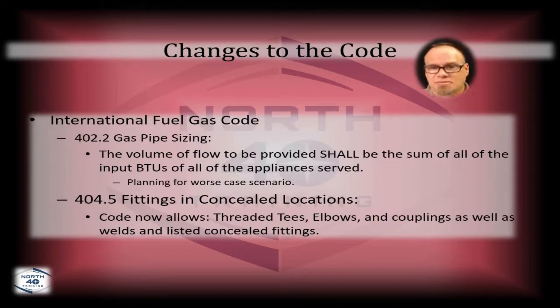4022 talks about gas pipe sizing. There used to be all kinds of tables and equations that you could use to tell you how big the gas pipe has to be coming into the structure. It's easy now. You have to do the same thing on a natural gas structure inside the city as what we've been doing on LP systems out in the country for decades.